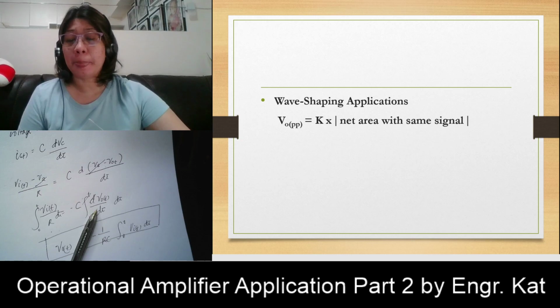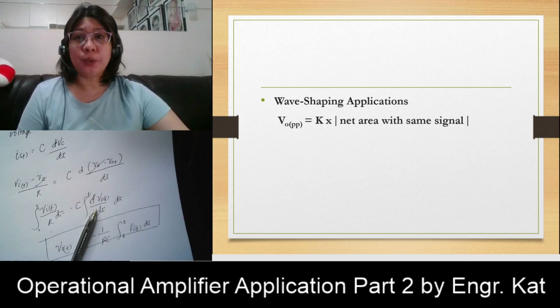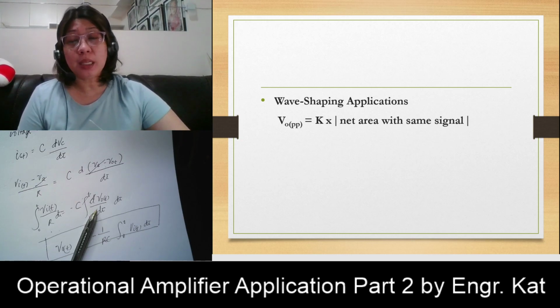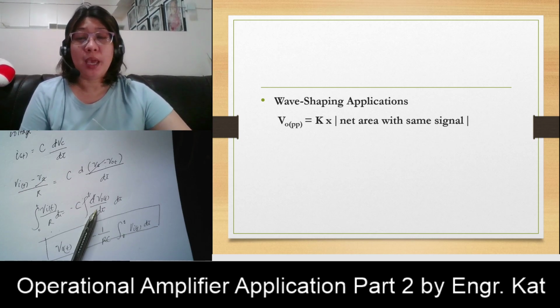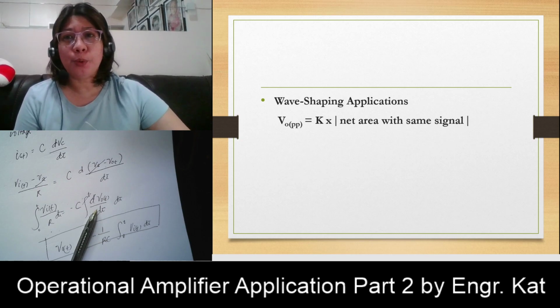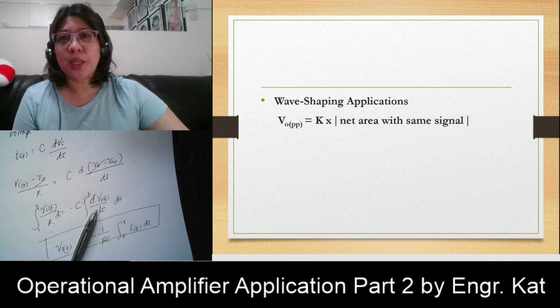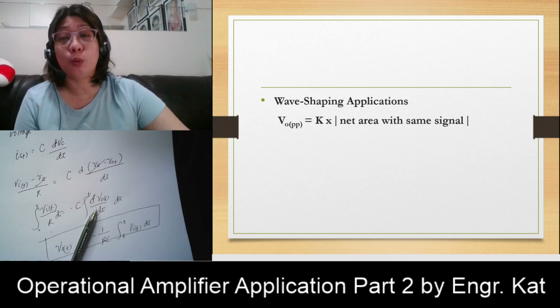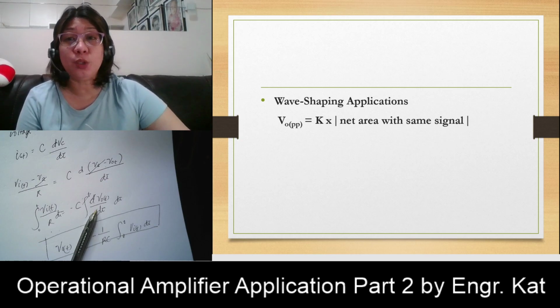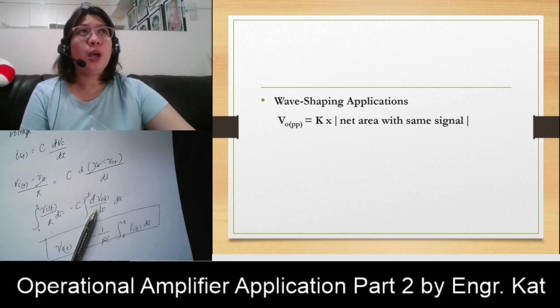Okay, so for practical application, the integrator is used for wave shaping applications. We have here an example wherein we get the value for the output peak-to-peak voltage, and the output peak-to-peak voltage is equivalent to K. Actually, your K is your 1 all over RC. Okay, so that is your scalar.